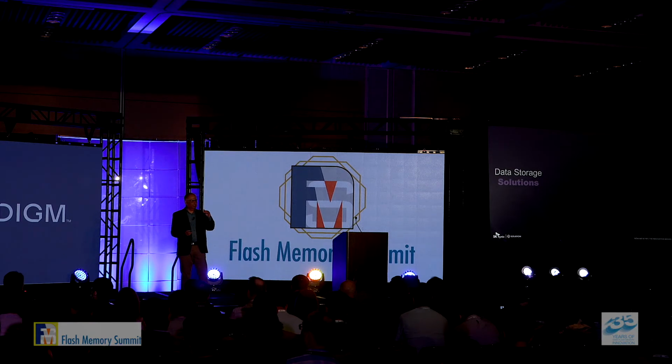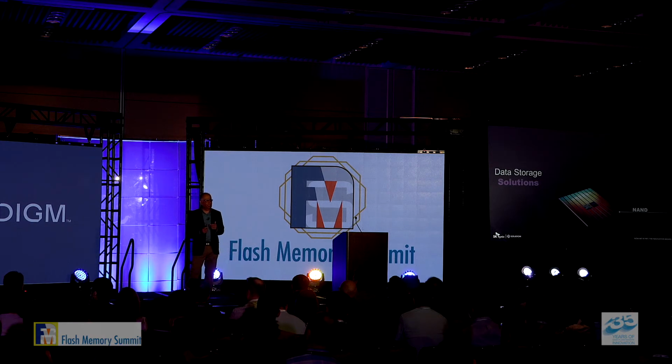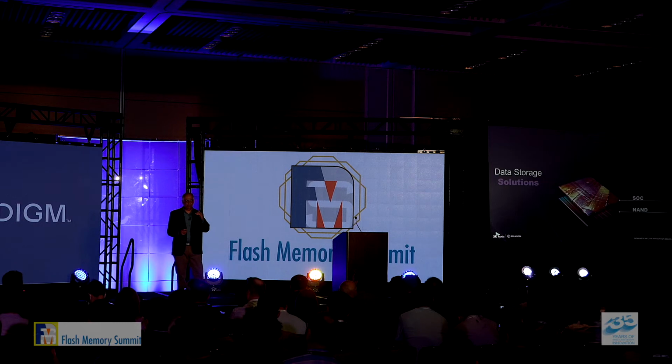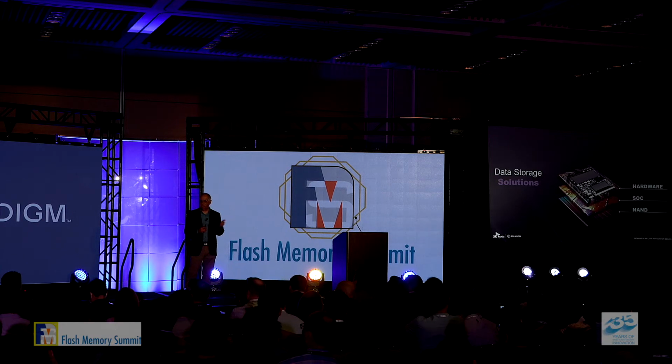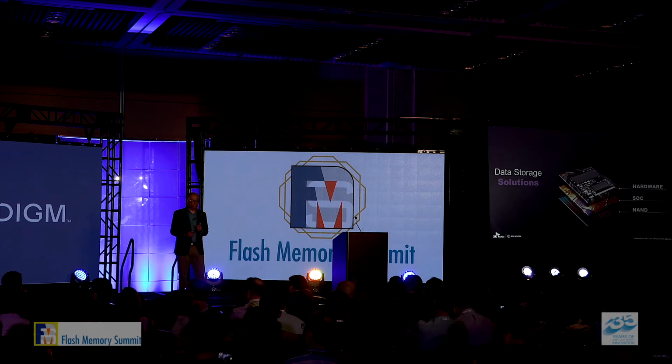Built on NAND brings in the SoC or the hardware layer. And once again, a good avenue for innovation like the EDSFF form factor that had its genesis in the ruler form factor, an innovation by Intel SSD Group in 2017. That form factor provides better manageability, serviceability, and thermal control for the data center. Built on that come another couple of layers with firmware and software that can then be tuned to provide a high degree of customization and personalization for the data center solutions. Let's look at how these layers can really be applied in the real world in the data center.